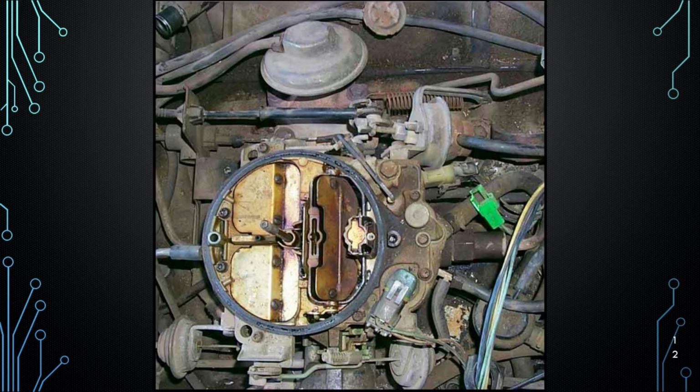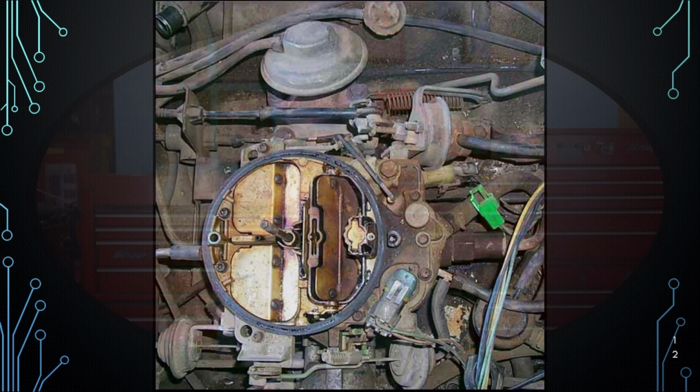I would tell you, when you put one on, this would normally cause a condition when you started the vehicle up where the vehicle would, we call it blubber. In other words, it would sit there and smoke and choke, and you often had to rev it up to try to clear it out. Then once the engine warmed up enough where the choke could release, it was fine. But the diaphragm would rupture and not apply enough force, or any force, to the choke plate, causing this problem. When they were bad, they would ultimately fill the crankcase with gasoline over time, and foul up the spark plugs so they would come out just black in color or even dripping with fuel.